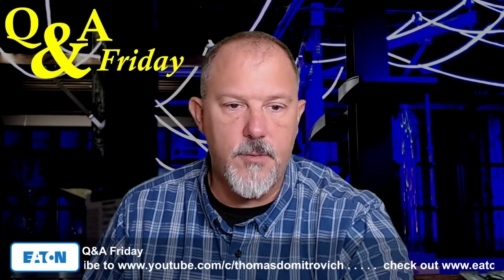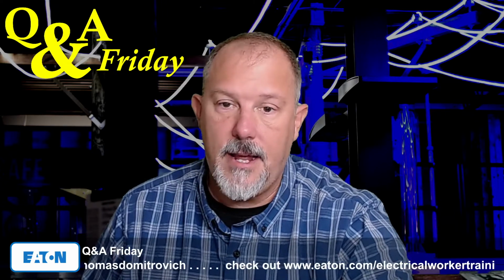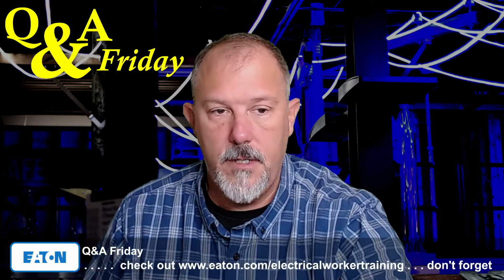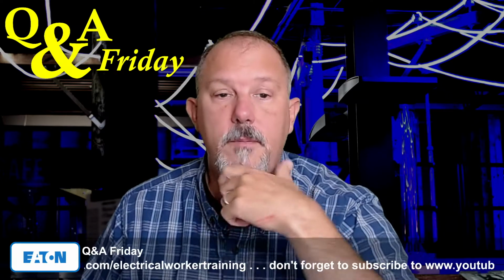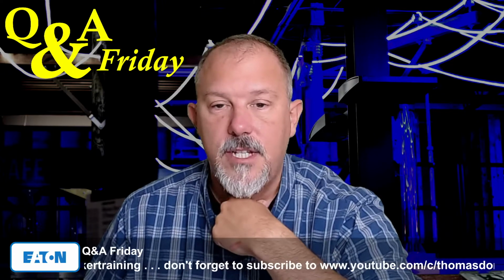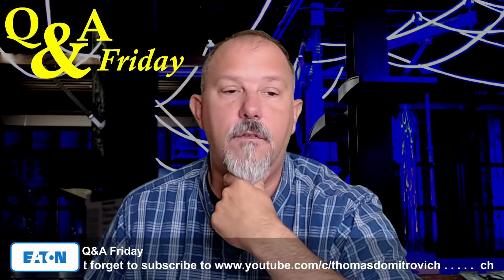Question about this language: the protection is required to be provided for the branch circuit or outlet. It doesn't say that the outlet shall have GFCI protection. Is someone to conclude that "for" would mean the GFCI protection be ahead of the outlet and not just at the outlet? It says it's being provided for the outlet.